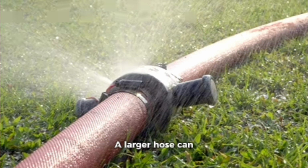Now that we know the current, we can choose the cable size. For 82 amps, a 16 square mm cable is typically recommended. However, for longer distances, it's safer to use a 25 square mm cable to minimize voltage drop and ensure everything operates smoothly.